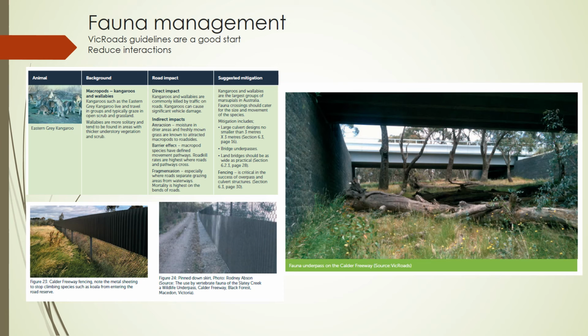So what we're going to propose is that we have a large scale mammal culvert that will allow the animals to run through. We don't have a very wide road, so a single culvert should be acceptable. Certainly not the bridge that's pictured in the left picture, but we are also going to put some fencing along the roads to dissuade the animals from entering the road in some of the kill zones, especially around the corners. And the key point is we're going to actually have to landscape these culverts so that they're effective in excluding the animals from the danger zone.